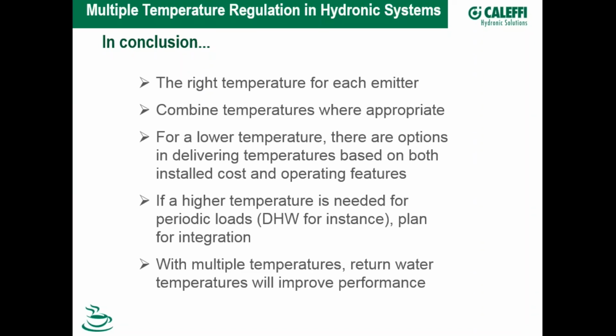The aquastat on the boiler was set so that whenever a thermostat called, the boiler went up to 200 degrees. Before I switched over to a condensing boiler, I wanted to know where my balance point was for water temperature and adequately heating my house. I took the aquastat and cranked it all the way down to 160. By dropping it down to 160, my water temperatures dropped, and amazingly, my house continued to heat.